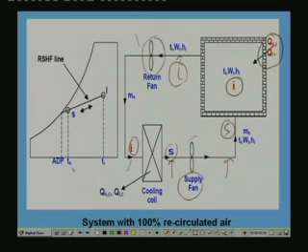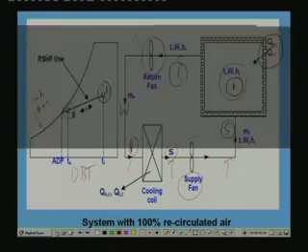So, you have the dry bulb temperature here on the psychrometric chart. As you know, on the y axis we have the humidity ratio, and this, as you know, is the 100% relative humidity or saturation curve. Okay, and point I is the state of the conditioned air inside the building, and point S is the state of the air at the exit of the cooling coil or at the inlet to the conditioned space. Okay.